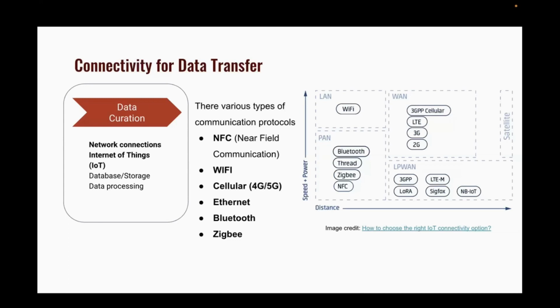The higher the frequency, the weaker the signal will be, because with high frequency you have a low wavelength. It cannot pass around your building or walls easily. So with all the new Wi-Fi routers, your signal might be limited to probably just your house, or sometimes you can get further away with an extender.